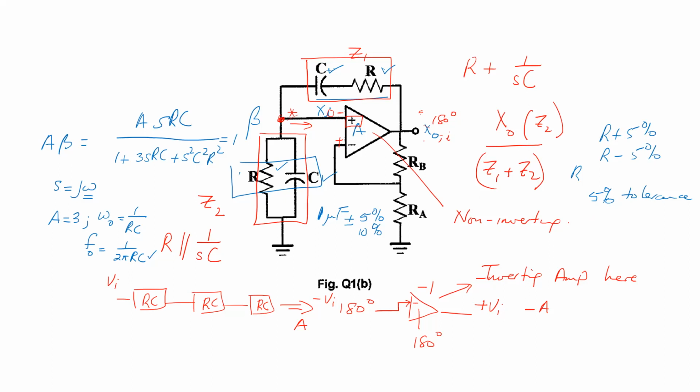And then you'll wonder why. You go back and try to figure it out, but wait a minute, I did all the theory, I did everything correctly, but the thing is not working. And 9 times out of 10 it will be because the resistors or the capacitors are not matching closely enough. Okay. All right. So that's sort of a practical slide.